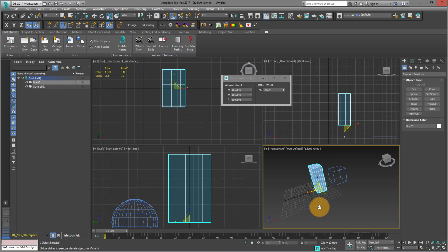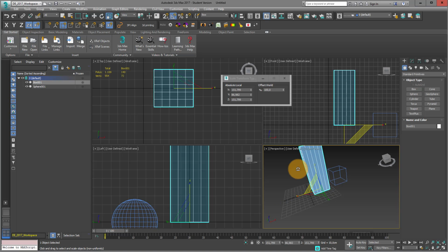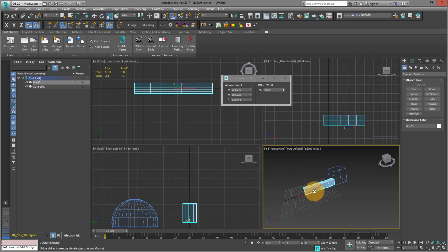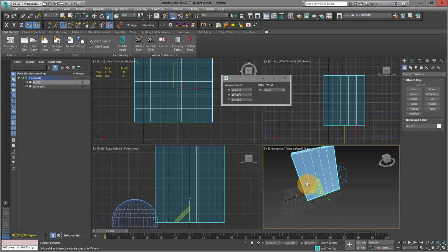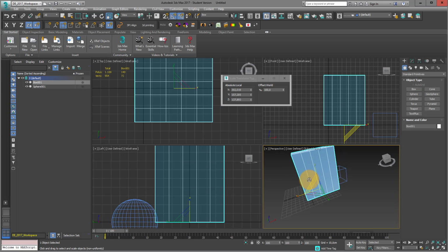If I just go and select only Z and Y, then I just scale it asymmetrically, and I can do it in all directions. And also here there's the option of percent snap toggle, so it now goes into steps, which you actually with right mouse click can adjust.